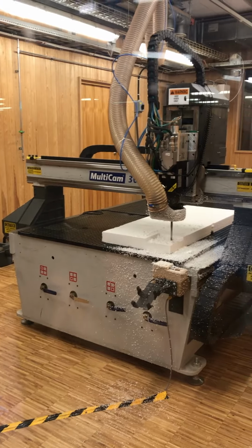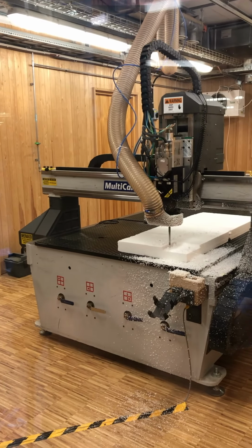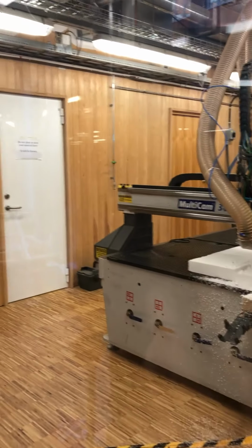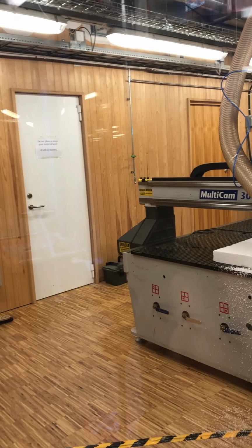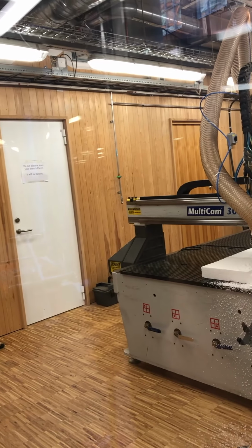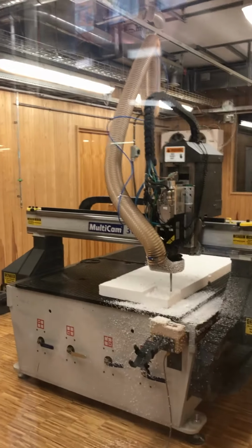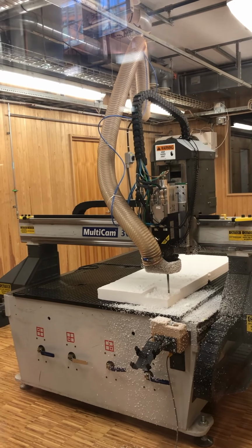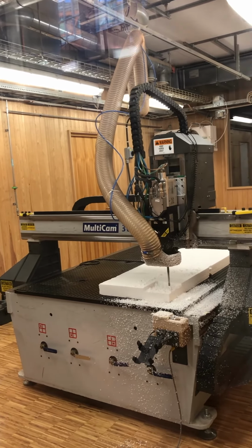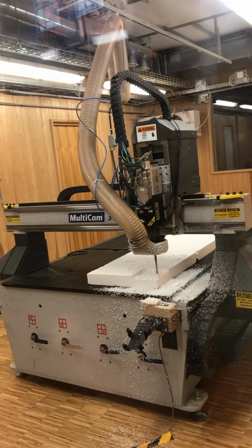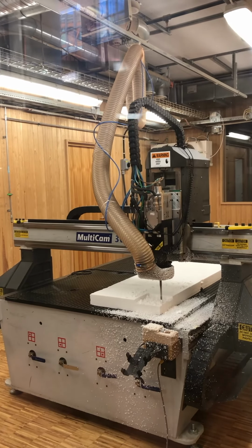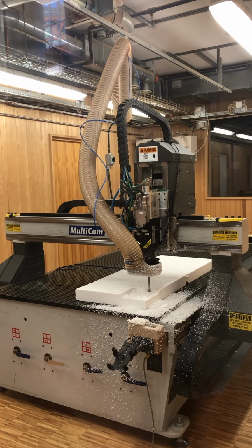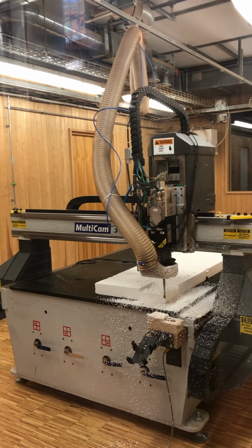And this part might be a little tedious, just looking at it, but it's important that you supervise, because things can happen. If you have done everything correctly, which one should make sure of, then since the maximum cutting depth is set, it cannot extend beyond that, so it will not be a problem, even if, like, it would be inches instead of millimeters and it would be way off.